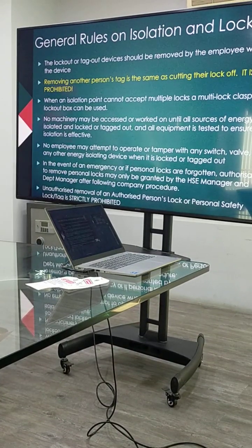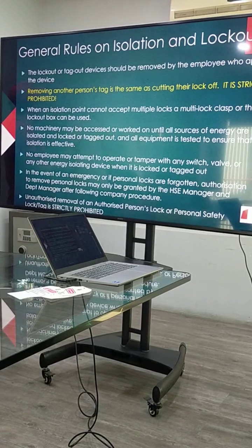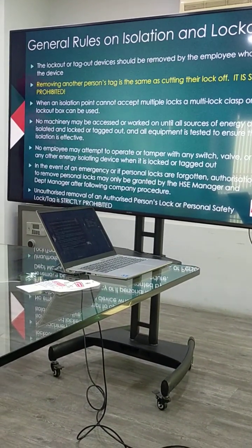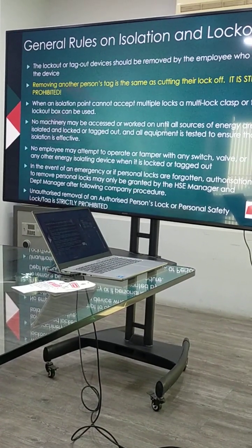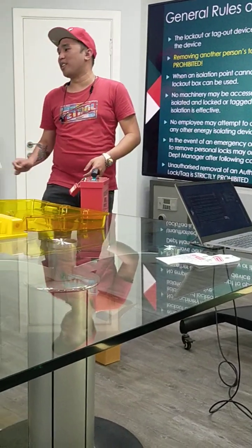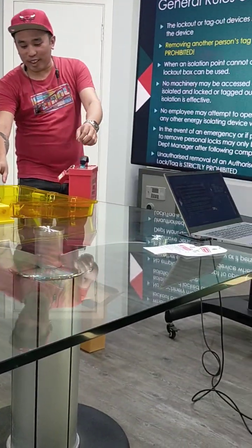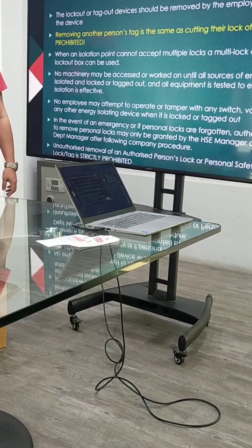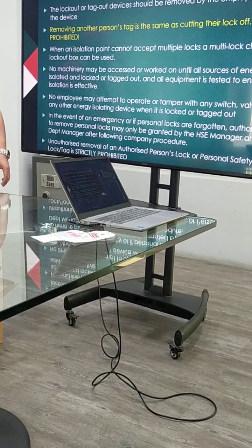Okay, we have the group lock. Our set of group lock is 12 padlocks, but only one key. So that 12 padlock, we will put all in for your 10 motors. Put the padlock and put the key inside. And the key will be for all 10.